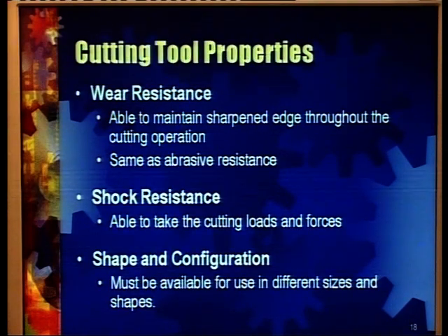The actual machining time is the time when the tool is actually engaged in the cutting operation, and the setup time and other non-productive times are the times required to unfasten the tool from the machine, to resharpen that tool, and then again mount the tool onto the machine post or wherever it fits onto the machine.